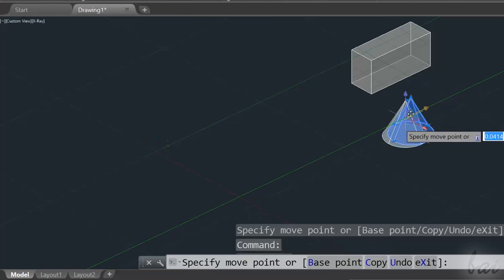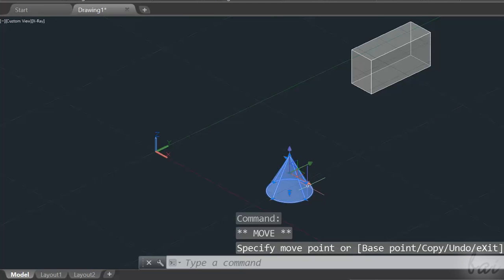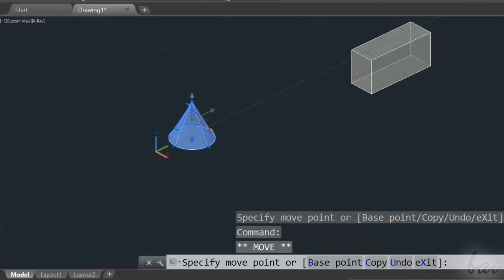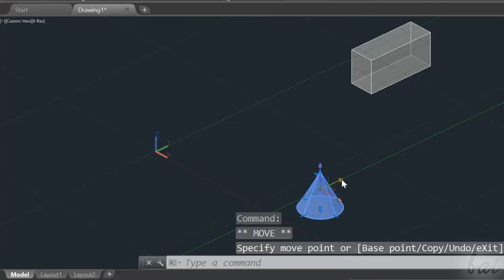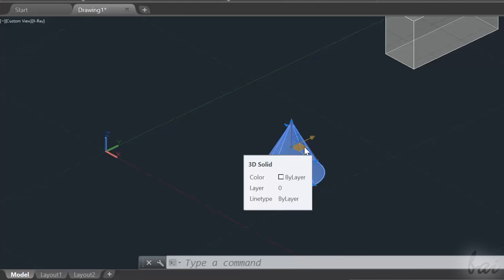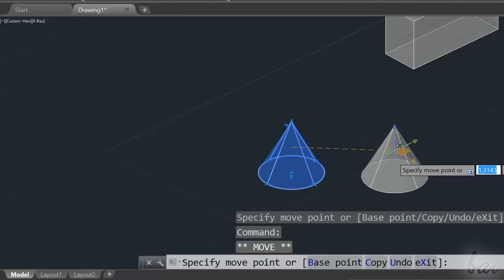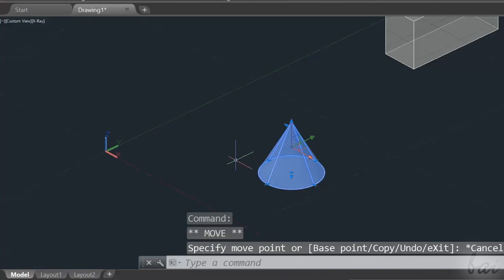By default, this gizmo is used to move the selected object according to defined directions. For example, if you click on one of the main axes, you will be able to move the object just along such direction. You can also click on a defined plane in order to move freely along such plane, so keeping constant the object position respect to the third axis.